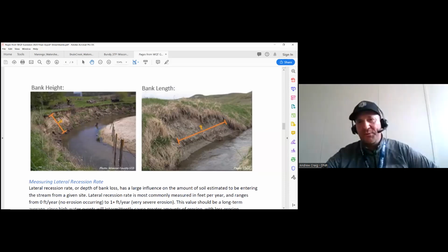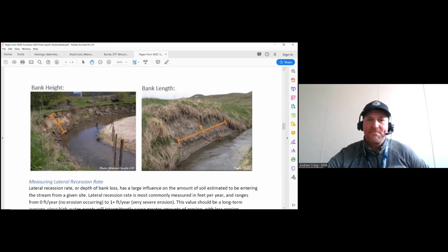And if you have multiple areas of erosion within the section of stream bank you may have been inventorying, you're going to want to take multiple height measurements and write those down and input them into the model to accurately assess the total erosion and pollutant loading from the cumulative of, let's say there's 4 or 5 of these sections along the section of stream bank you inventory.